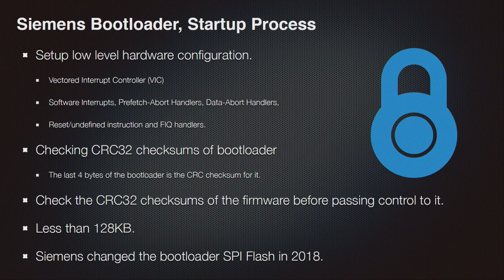A thing to note here is that it's using CRC32, which is only something that can check for non-intentional changes to the firmware. So if physical memory was corrupted in some way, but if somebody got control over this, it's not a cryptographically secure checksum. So the bootloader doesn't perform any cryptographically secure checks just before running the firmware image, which is interesting to note.